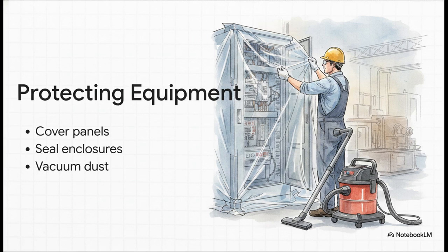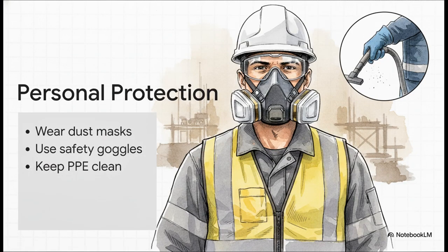You want to extract the dust, not just shuffle it around. Your personal armor is just as crucial as the site barriers. This means you must wear appropriate dust masks or respirators, especially when you're anywhere near dusty operations or handling sensitive gear. You're also going to need safety goggles to stop dust from getting into your eyes and blinding you during a critical task. But here is the detail that really separates the pros from the amateurs.